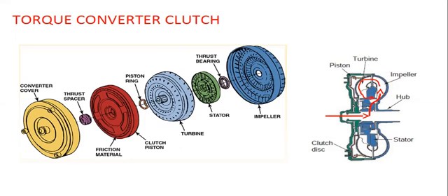During the lockup mode, or the clutch engaged mode, the shift valve moves and reverses the fluid path. This causes the fluid to move to the rear of the piston, pushing it forward to apply the clutch to the shell and allowing for lockup. Fluid from the front side of the piston exits through the turbine shaft that is now vented at the switch valve.